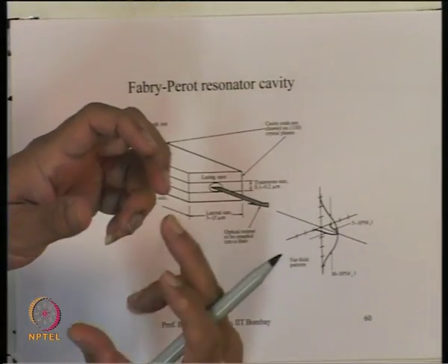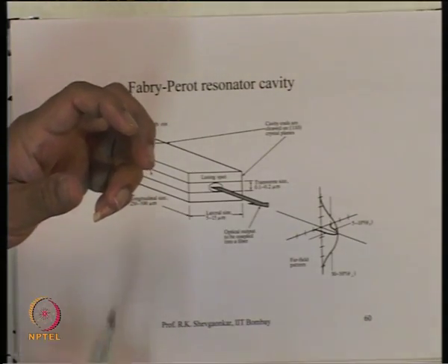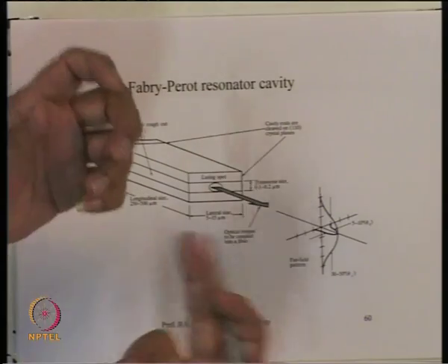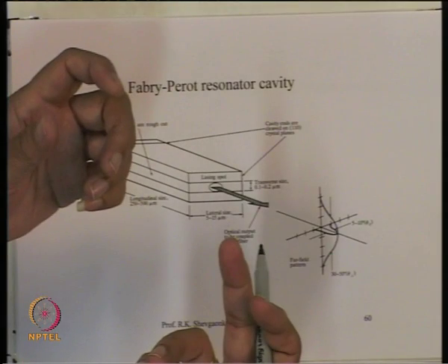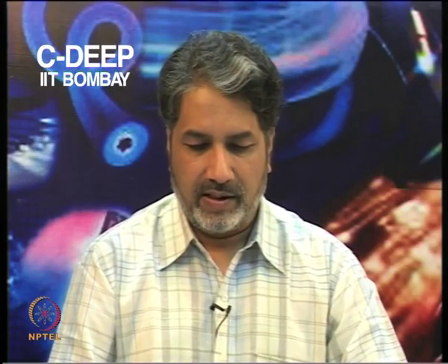After the current crosses the threshold value, suddenly the process turns into the stimulated process. So, the angular cone is no more 180 degrees, but suddenly gets narrow like this. So, from this direction it looks as if the device is switched off, because now the radiation is going into a narrow cone. Then I have to orient the device properly and look into the device to really see the radiation coming out of that.